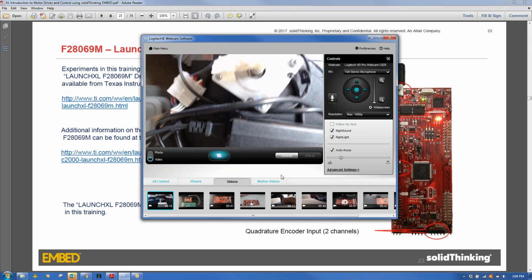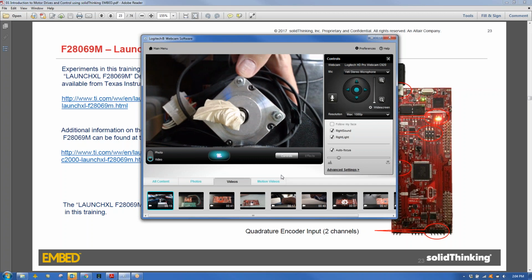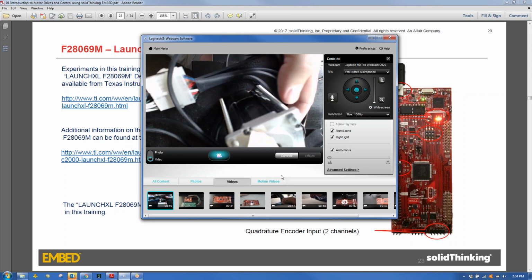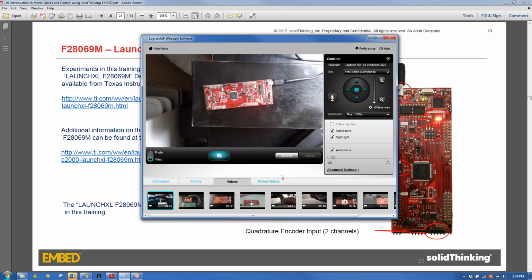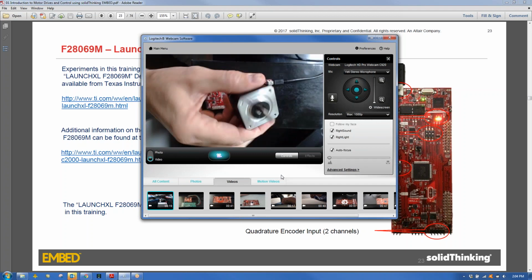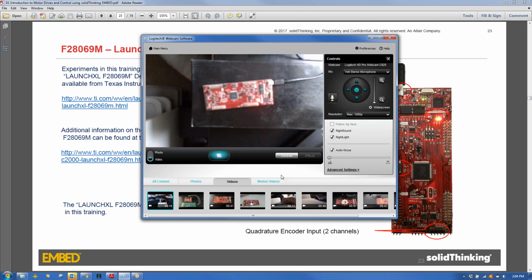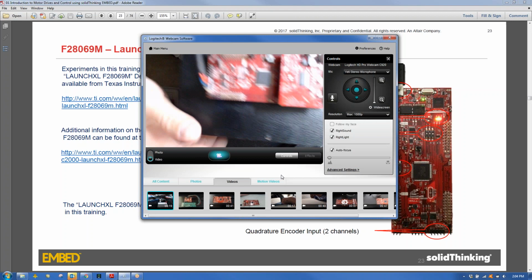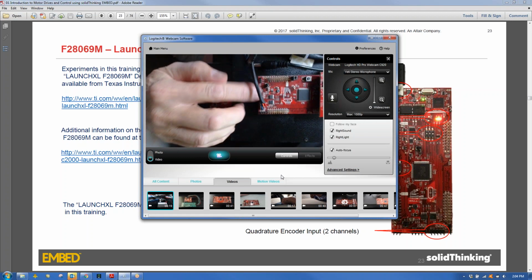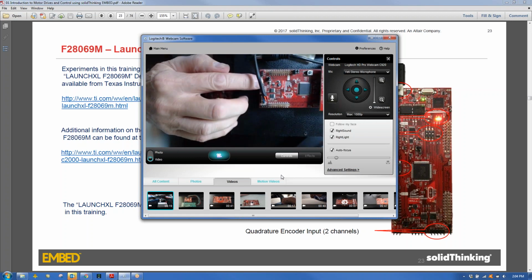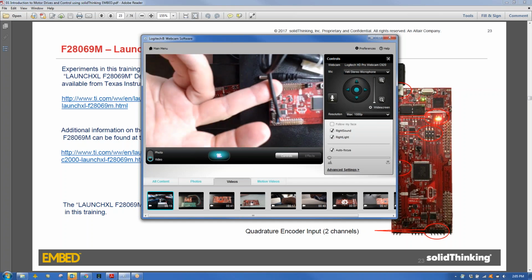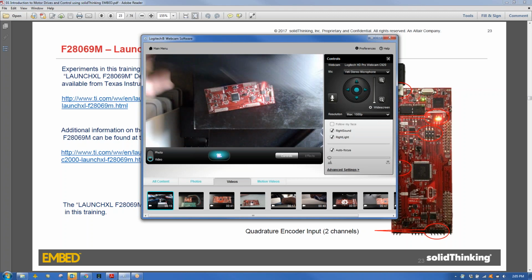In this example that I'll show you tomorrow, this is running a fairly good size permanent magnet motor. I think this is a 23 size motor, so it's pretty significant size-wise. It's much bigger than these smaller step motors that I have here. And that's all you need. You don't have to do any electronics. Everything works on this. This is an encoder input, so there are actually provisions for two different encoder inputs here. This particular motor has a built-in encoder, and that's what I'm using here for the encoder feedback to control position or speed.